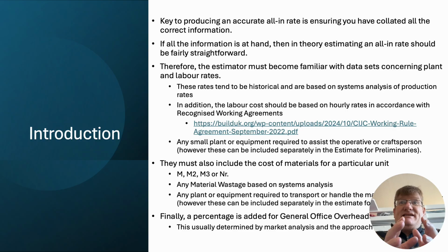This is a mathematical exercise, but fundamentally it's a much more realistic one, because you're breaking everything down into plant or machinery, labour, and materials, and all the intricacies and nuances which go through each of those. For instance, I'll give you an example. Materials would be broken down into wastage factors. You might have to convert tons to metres cubed, or metres cubed to metres squared. With bricks, you might have to reduce it to one brick.